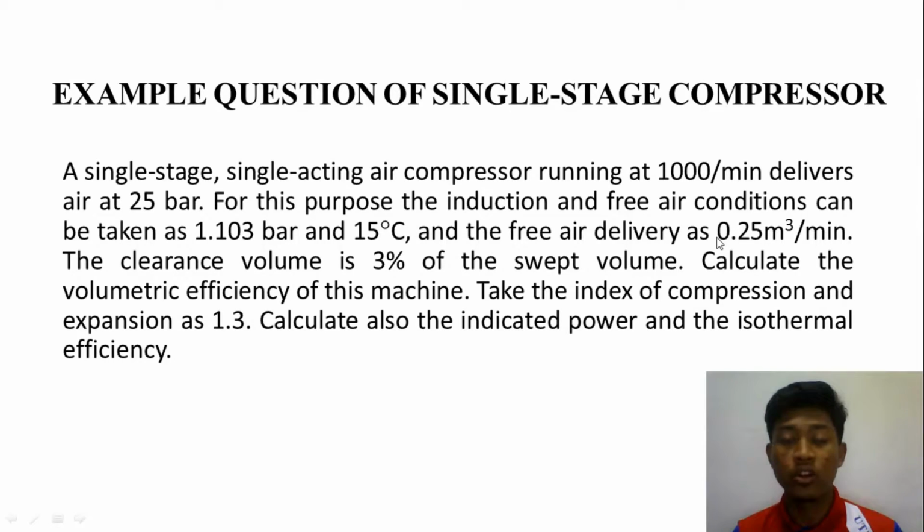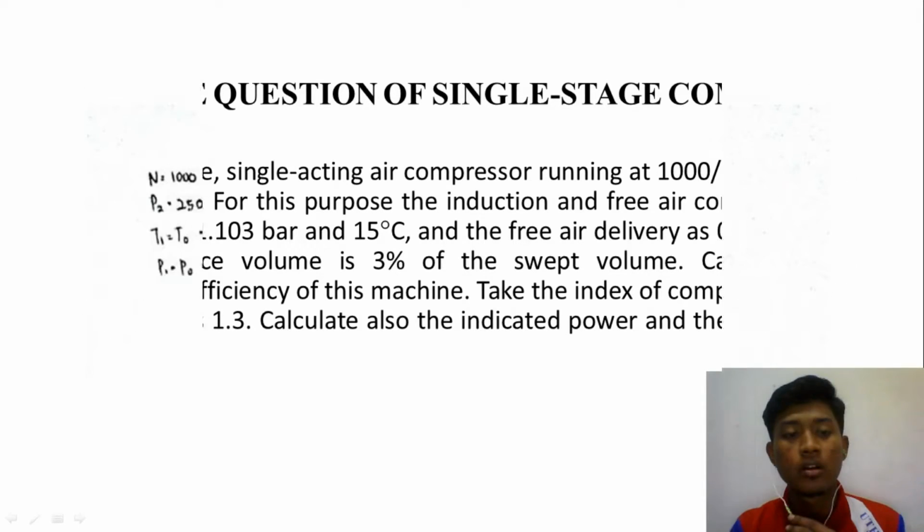The clearance volume is 3% of the swept volume. Calculate the volumetric efficiency of the machine. Take the index of compression and expansion as 1.3. Calculate also the indicated power and the isothermal efficiency. So I will show the calculation of this question.